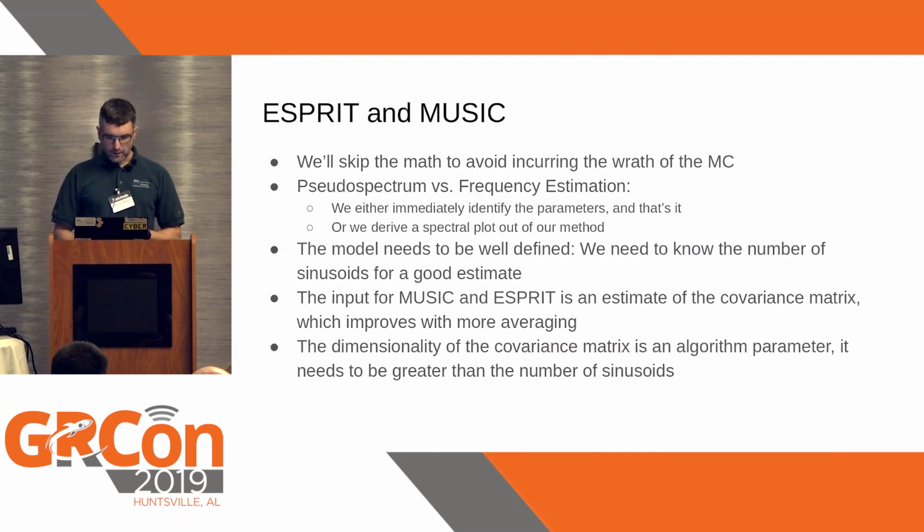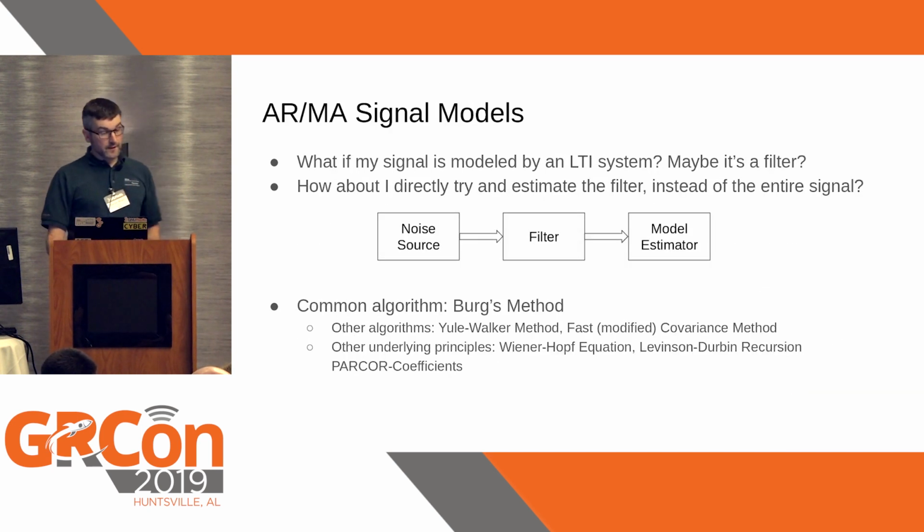Okay, so we changed our thought pattern. Said, okay, I'm going to say my spectrum is a bunch of sinusoids and noise. That's it. Is there anything else we can do? Yes. There is a similar but different way of thinking about it, which is something like this. Let's say the signal that I'm estimating is actually modeled as some noise, which is then going through a filter.